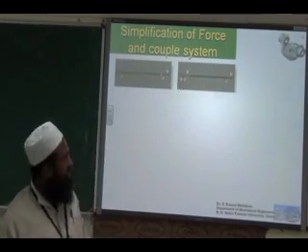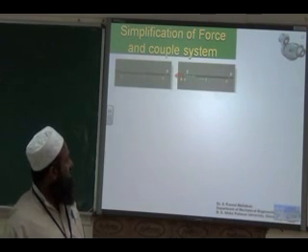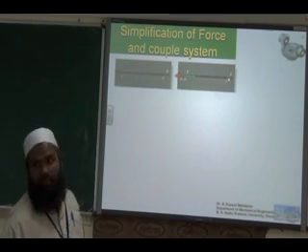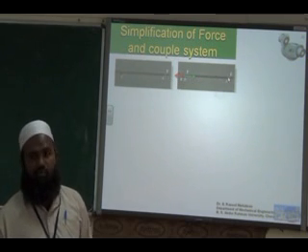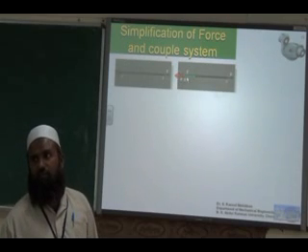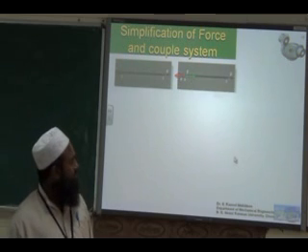We'll get only one force remaining. Like this, we add two forces. This green color force is parallel to our force F. The red one is opposite to force at point A. So the opposite red force and the force at point A will get cancelled because they are equal and opposite. We will have only the green vector shown here. Only one force exists. So we got the force transmitted to point B.